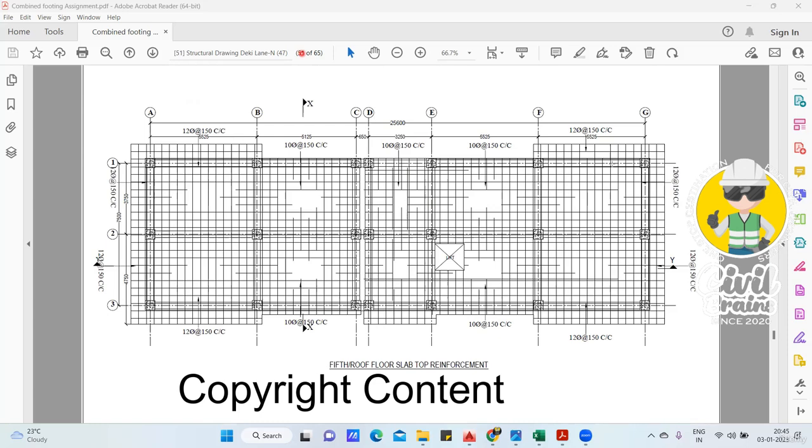Again, this is all cantilever part. This is all cantilever part. So I didn't teach you, but I think you can do all these things. Whatever cutting length you used to take, we used to take the cutting length up to here, right? This bar we used to take up to here. But now what you are supposed to do, you have to take it up to this length. Just add this offset. Let us say if it is 600 mm, that 600 mm you add to the cutting length you got.